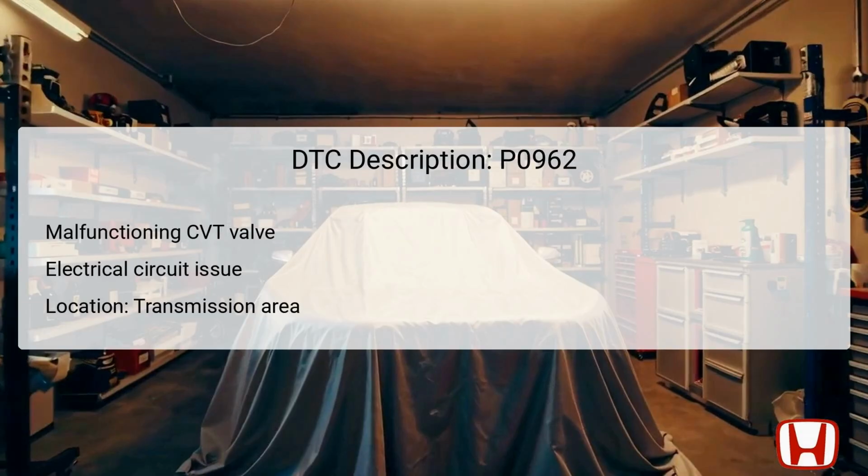The DTC P0962 indicates a malfunction within the CVT drive pulley pressure control valve circuit, pinpointing it as an electrical issue. Specifically, the code suggests that the voltage or current is low within the circuit controlling the CVT pressure control valve. This component is typically located in the transmission assembly. Its role is to regulate hydraulic pressure, impacting the overall transmission performance.